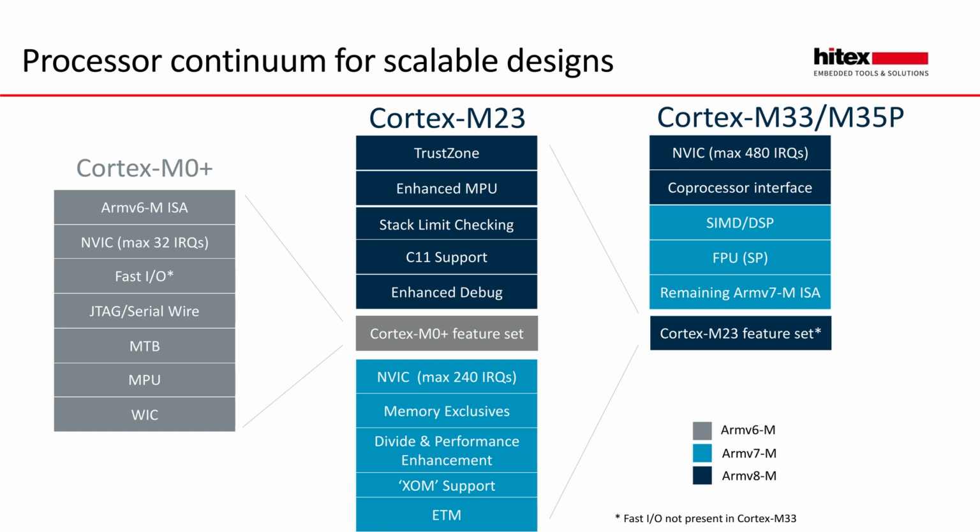Now, within the Keil tools, when we're defining our secure project, we can select the software model. So here we can say that we're building for the secure world. We also have a choice of the compiler library that we're going to use, so microlib or the default ARM compiler libraries. And then normally in here, we can define the memory layout for the target by defining execution and